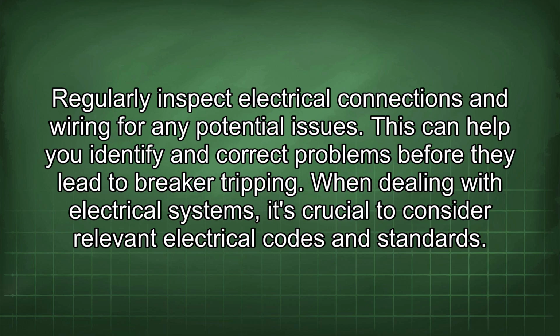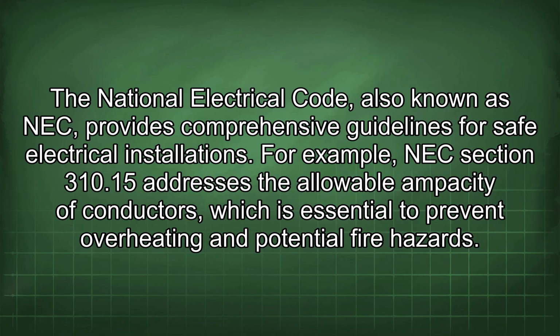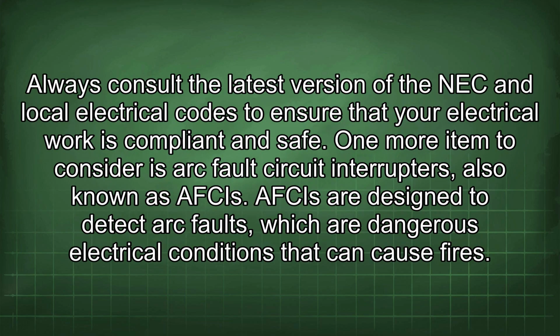When dealing with electrical systems, it's crucial to consider relevant electrical codes and standards. The National Electrical Code, also known as NEC, provides comprehensive guidelines for safe electrical installations. For example, NEC Section 310.15 addresses the allowable ampacity of conductors, which is essential to prevent overheating and potential fire hazards. Always consult the latest version of the NEC and local electrical codes to ensure that your electrical work is compliant and safe.